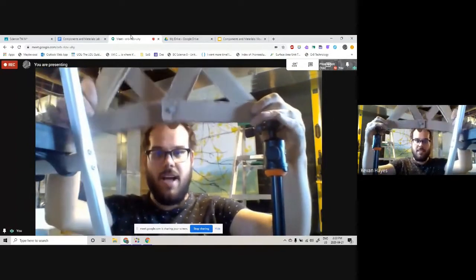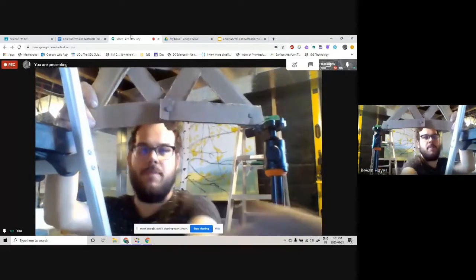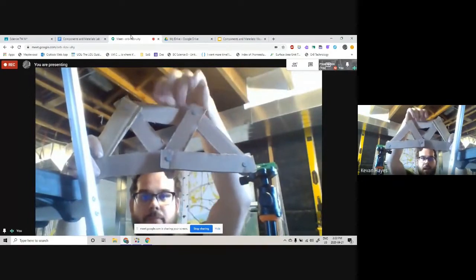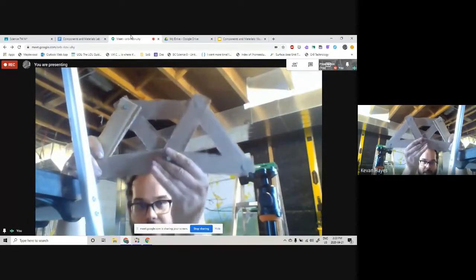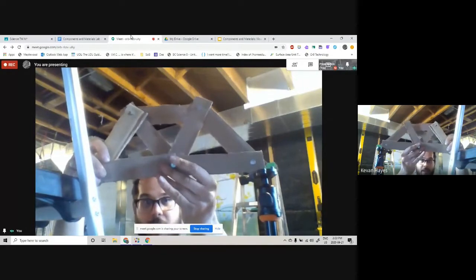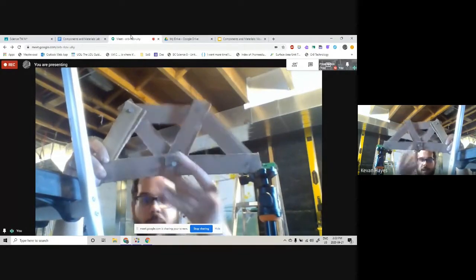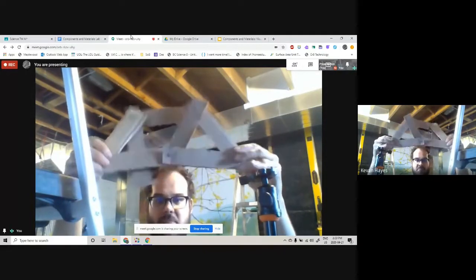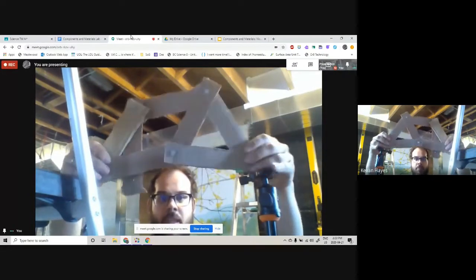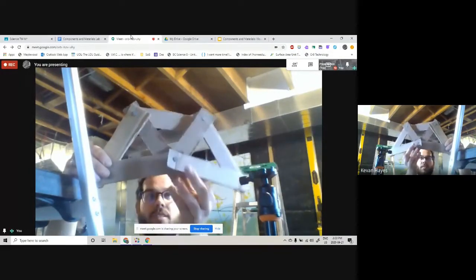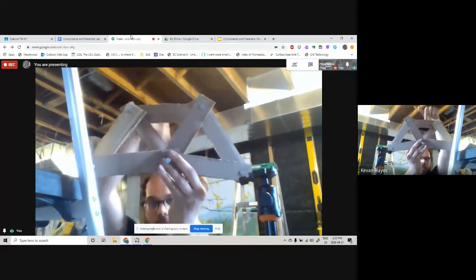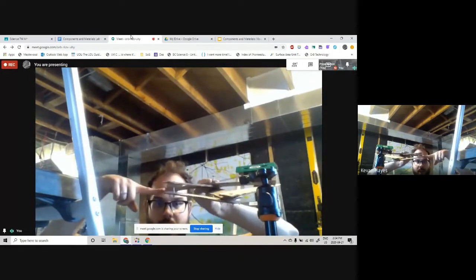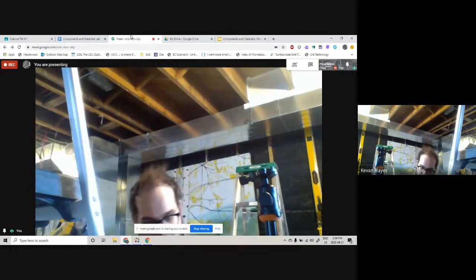And so a truss, like a beam, can span over a gap. And in this case, if I apply a force to the top or to the bottom, like if I try to pull down from this or hang something from the middle, this is a pretty sturdy shape. Again, it's just made out of pieces of cardboard, but it's pretty sturdy. It's not sturdy this way. It's not sturdy this way, but it is sturdy so long as the forces push through the plane of the material. So any force going this way or this way, it's going to be able to withstand those forces.